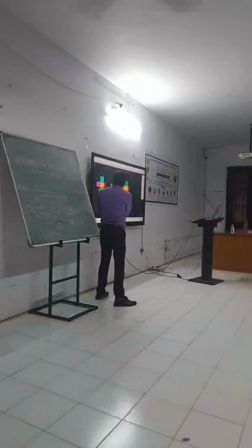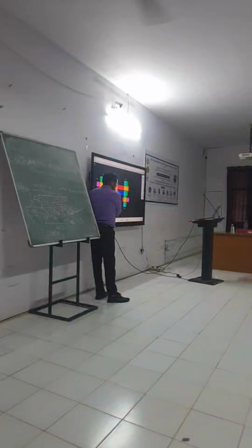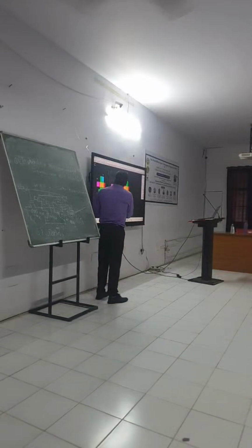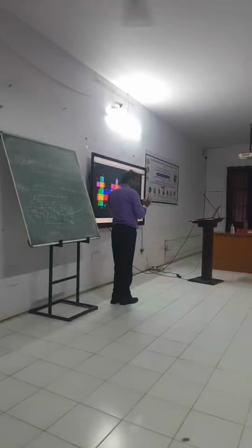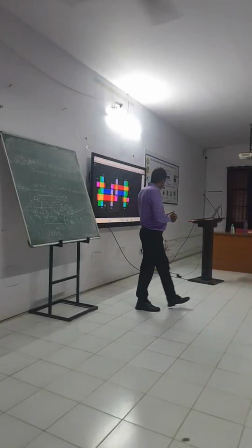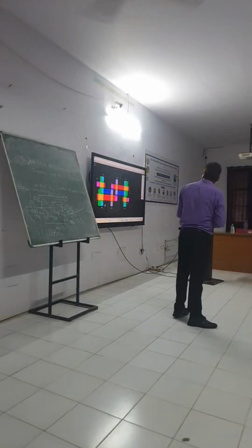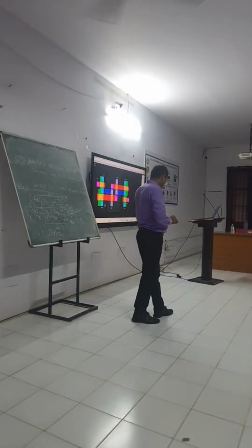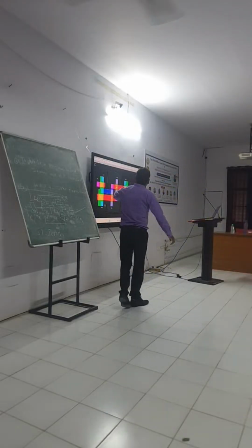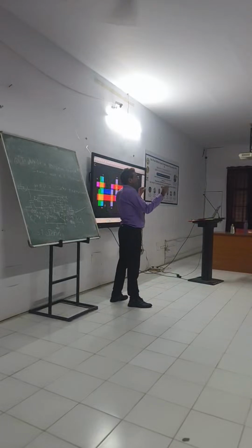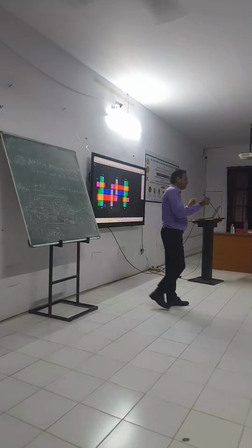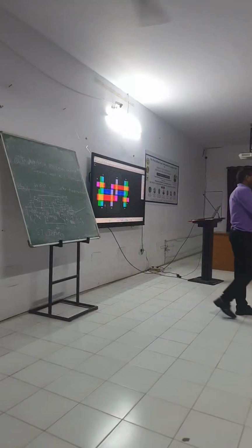According to the layout design rule, here there should be 6 lambda space. If you are not putting this 6 lambda space, then an error will come. Similarly, this width should be fixed. The lambda design rule or micron layout design rule mentions very clearly the spacing between two layers, width of the metal layer, width of the polysilicon, width of the P diffusion, width of the N diffusion.